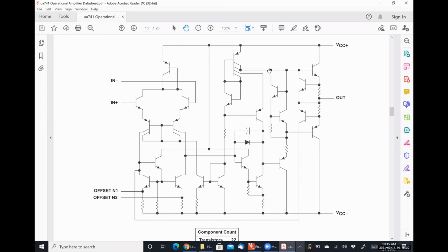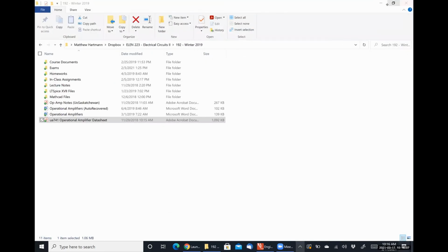We're going to learn about an awful lot of these guys, actually. Over there at the input, that's what's called a differential pair. It's being loaded, so there's a diode connected PNP BJT up there at the top. That's what's loading in, getting our power supply voltage. Down here at the bottom, we have current mirrors, all kinds of good stuff. You're going to learn about the building blocks of almost all of this in this class. So, all right, we can get rid of this. Just wanted to explain what was what.